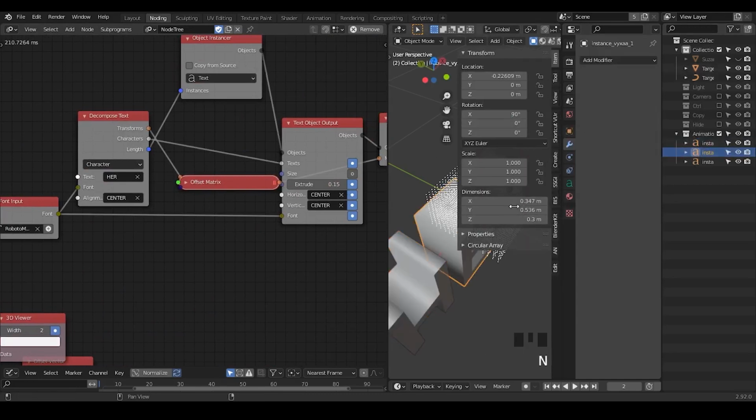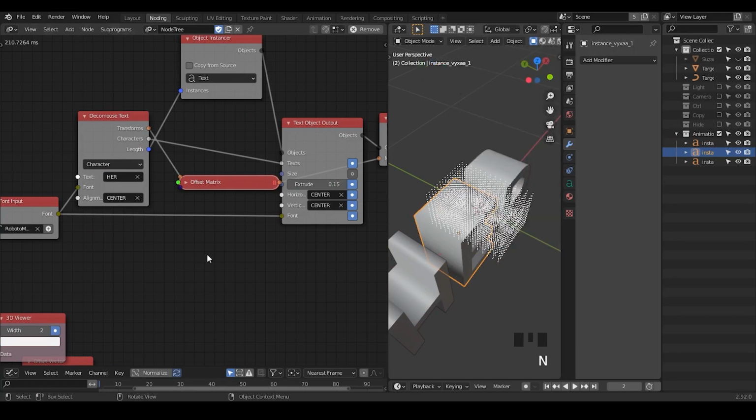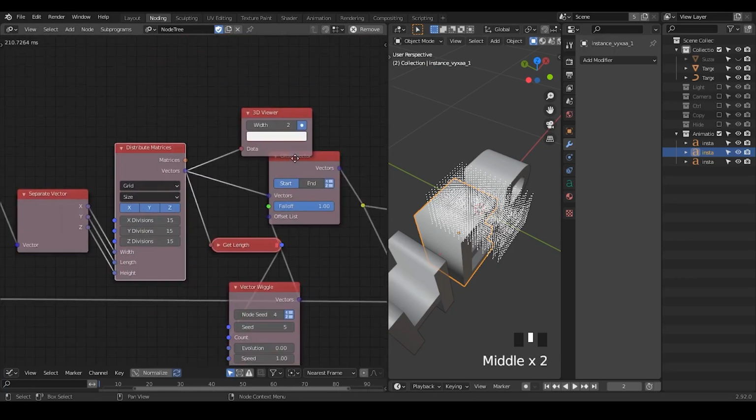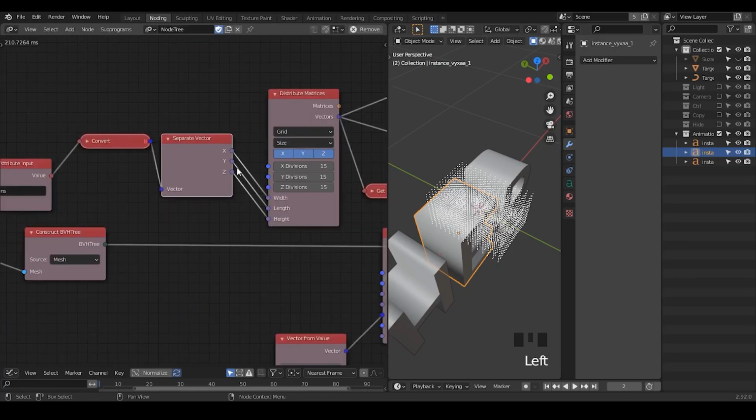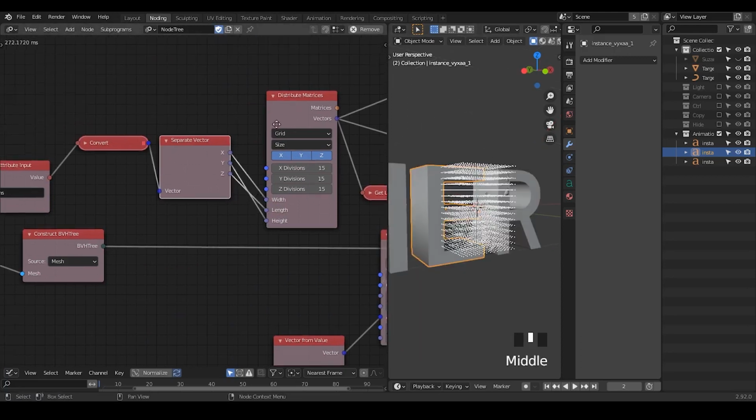So to Blender, even if you rotate or not rotate that, the dimension is not changed. Dimension does not change based on the rotation. So it's still lying down in Blender's opinion. In short, the Y is actually Z, the Z becomes Y. So now we actually stand up.